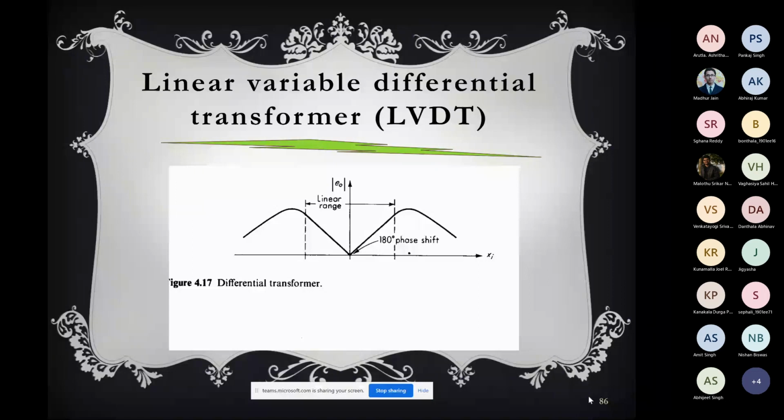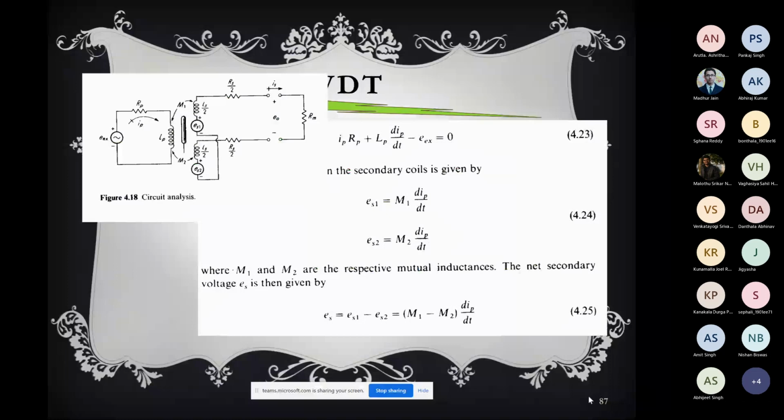Fine. Next thing is that the meter cannot follow a very rapidly changing core position. Why? If the core position is changing rapidly, the output voltage amplitude modulates the sine wave, and demodulation is necessary. I'll come to it, how a time varying voltage can be measured. Before that discussion, let's leave this point.